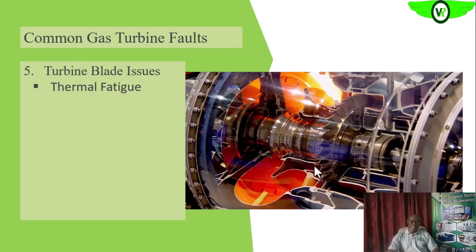Are we getting it? Then the fatigue, in the sense that as you are heating like that, the normal strength of the blade material itself will eventually be lost. Once fatigue sets in, it can cause the loss of that particular blade. And that normal heating can also cause creeping of the blade material. So we have the creep effect.